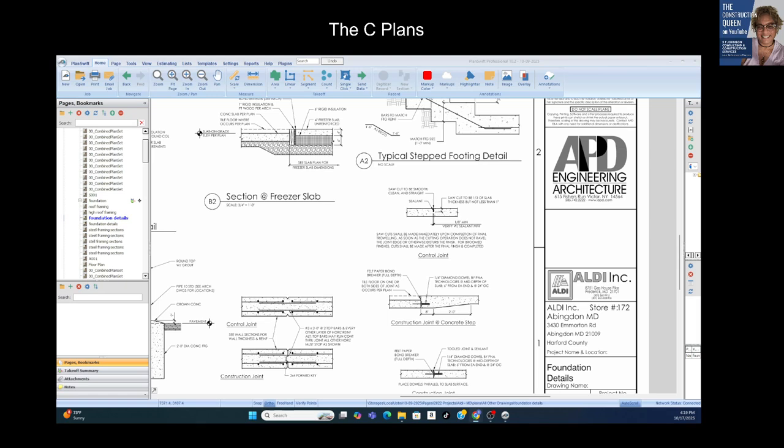So, common structural request for information triggers: missing beam and column connection details. You can't guess on those things, okay? And so you really do have to know if there is any rebar that is shown and doesn't give you the exact number. You've got to know, okay? You have to know the footing depth, those things, okay? And I mean, it's just important. So those are the things you really want to ask them about. You don't want to guess, okay? What else?